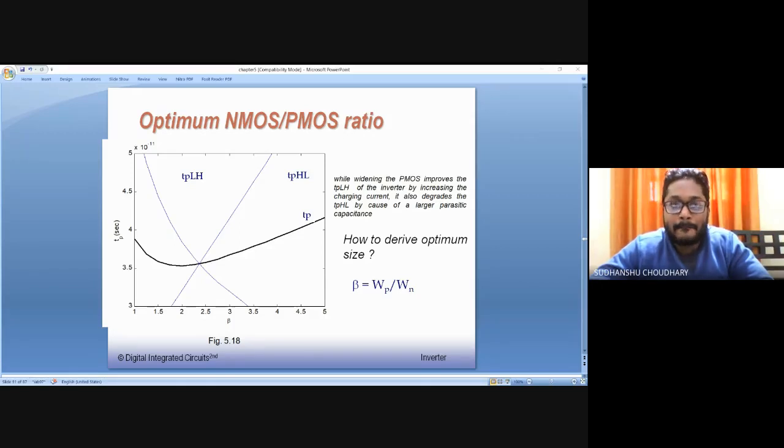Yeah, anything else? Sir, if VDD is less than VTH also, the CMOS inverter works, sir. Can you please repeat your question, and can you please speak louder? If VDD is less than VTH, we reduce VDD. Okay. Then also the CMOS inverter circuit works as it is, like the voltage transfer characteristics will be as usual. Yeah, correct. So the characteristics are still there. I mean, the inverter characteristics are still seen at VDD even below the threshold voltage.